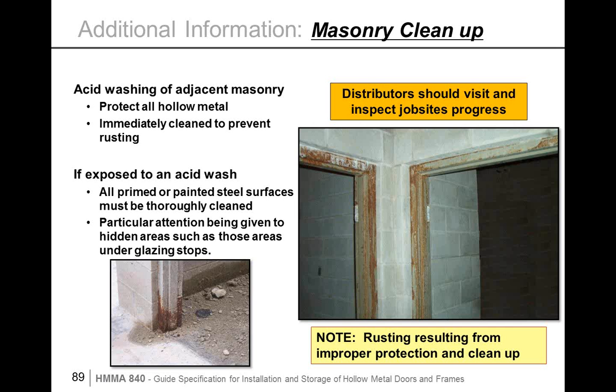The frames are always acid washed prior to finishing, and it's critical that the acid wash is cleaned up properly. If there's any type of rust showing up, it's the contractor's responsibility to prime, reprime the products before excessive rust shows up. This type of picture, and these are actual job photos used in back charges, is just total neglect by the contractor in the construction phases. It's critical to have the support when the job is coming to completion, and when I say support, I mean the inspection and the photography.